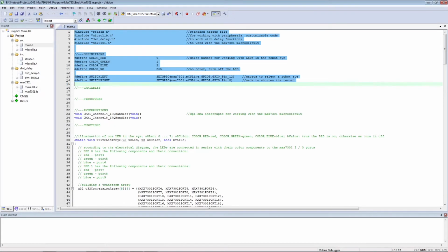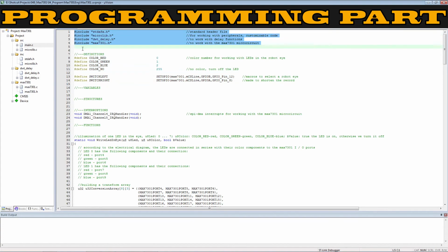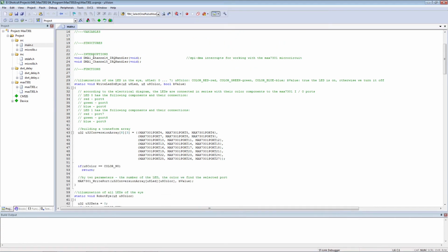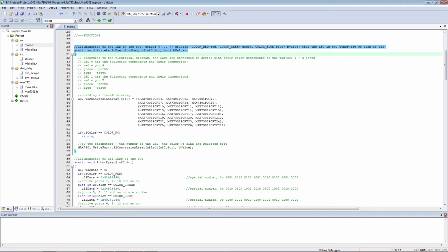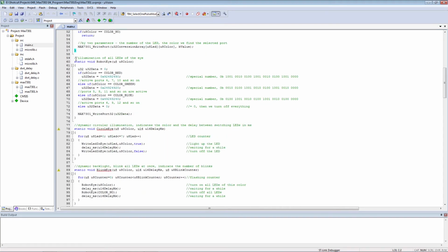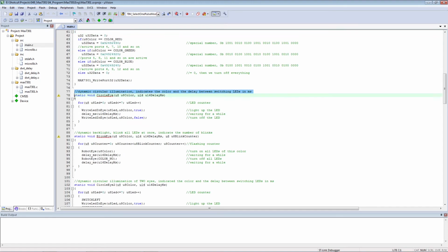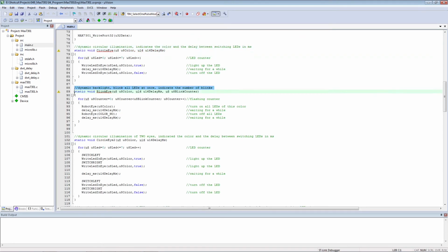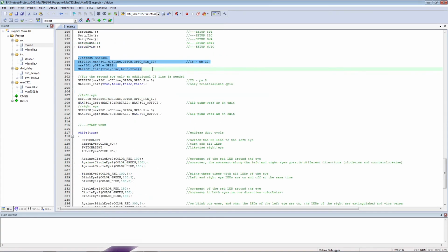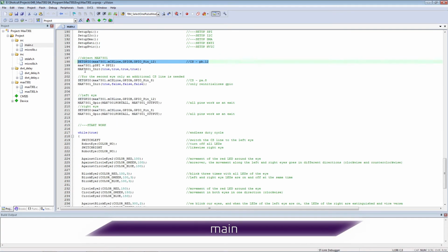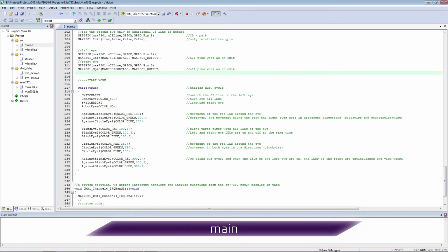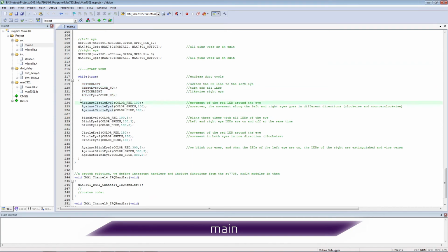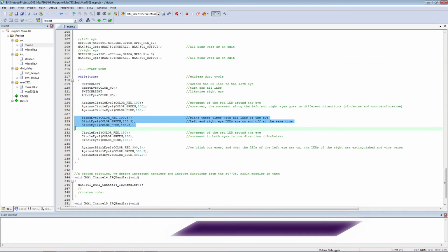Consider the control program. The main file contains functions for working with LEDs. You can separately control the color components or change the LED data from the entire group at once. Dynamic functions for circle and sequential blinking are also written. To work with the expander, a special object has been created, for which the CS line and the working SPI interface are indicated. The functions allow you to work with individual ports in turn, or write to all ports at once. We blink beautifully in an endless loop.